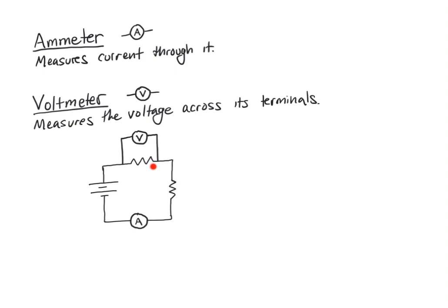Some would go through this first resistor, some would go through the voltmeter, then they would recombine and both go through the second resistor, in which case the current through the two resistors wouldn't be equal anymore and our circuit would actually behave fundamentally differently. So we want to ensure that our voltmeter has the properties needed so that that doesn't happen. We want to make sure that no current passes through the voltmeter. Part of your next assignment is to figure out what property the voltmeter should have so that that's the case.